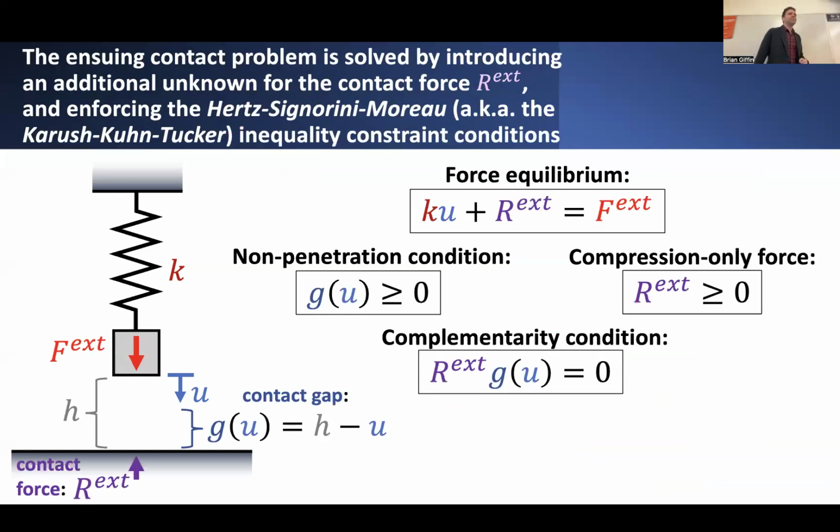All right, so putting all these different conditions together, it's worth noting that in general, we could treat this reaction force as perhaps existing even in the absence of the block coming into contact with the floor. However, if there is some kind of open distance or separation between the block and this rigid surface, then there really shouldn't be a reaction force here. Under those circumstances, we insist that the reaction force should just be equal to 0 if this gap between the block and the rigid surface is open.